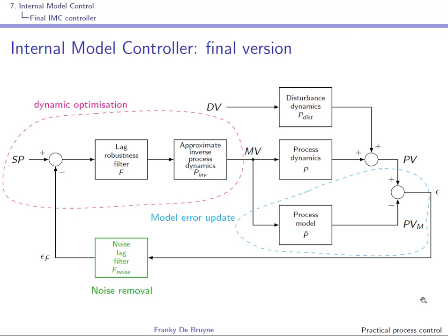Well, let us make the link with the step 3 internal model controller, and we'll do this for a process that is a Broida model. So we'll have here Kp over Ts plus 1 and the exponential of minus theta s, and of course we'll construct the IMC controller using a model, right?